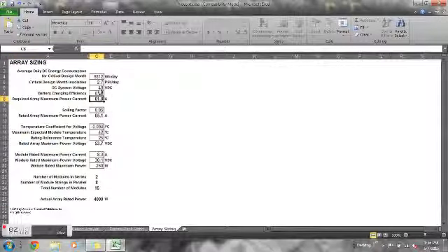The required array maximum power current is determined from the daily load requirement and insolation for the critical design month, along with the DC system voltage and estimated battery charging efficiency. The battery charging efficiency is usually about 85%. The result is seen right here as being 61.8 amps.